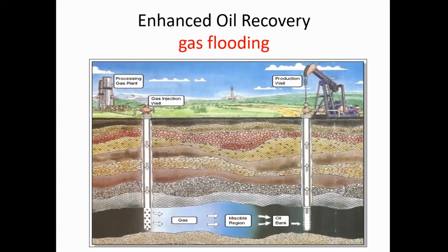Can I use, in the producing well, a production pump, such as rod sucker pumps, or maybe I use what they call ESP, and on the other side I do injection, a tertiary recovery? The answer is yes, you can. Here we have a tertiary injection well, and here I have a pump producing well. And nothing wrong with that at all. Both of them are applicable.